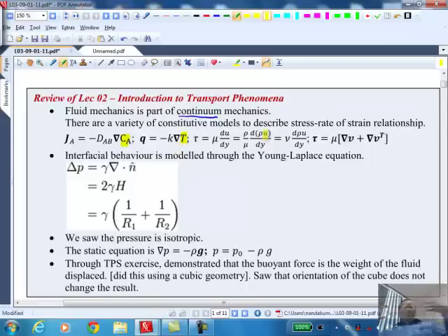But there is a similarity in these three phenomena, the so-called unified way of looking at transport phenomena at the molecular level, the way that they exchange mass or heat or momentum due to molecular interaction. Because we are not looking at it, we said we are going to write these constitutive equations that capture what happens at the molecular level. These are just constitutive empirical equations. Not all materials need obey them, and we saw examples of non-Newtonian fluid as well.